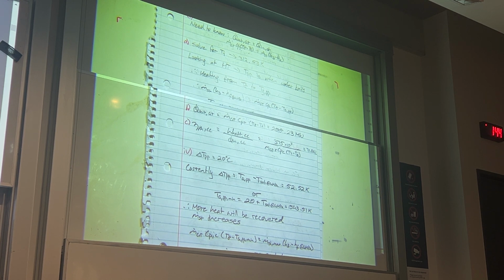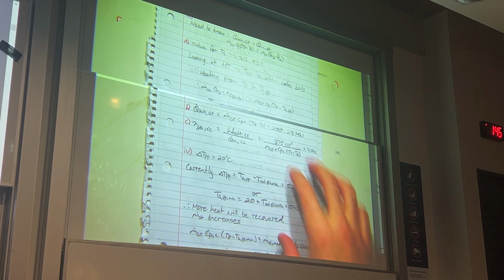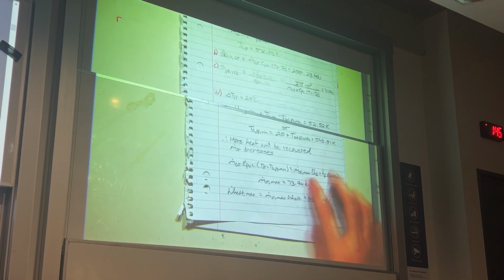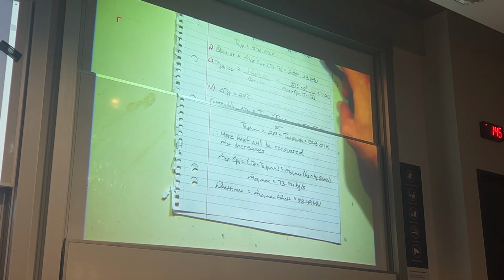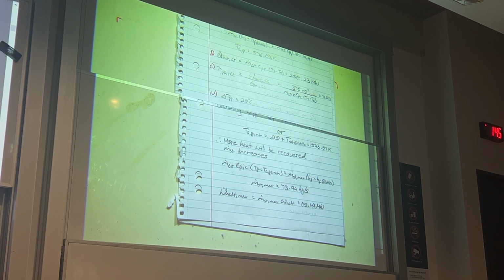But because we're fixed within our cycle, what's the only way to exchange more heat through that process? Did you yell out the answer? Also, think back to your refrigeration prac. How did we increase heat transfer? Yes, exactly. So if we're rejecting more heat through our heat exchanger, we're going to need a higher flow rate if we're operating at fixed temps. So knowing that, we can use this energy balance here, the same one that we used to find our pinch point temp, except now we're going to find our new steam flow rate.